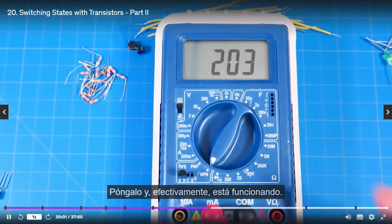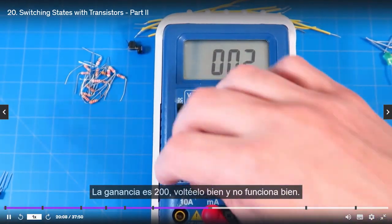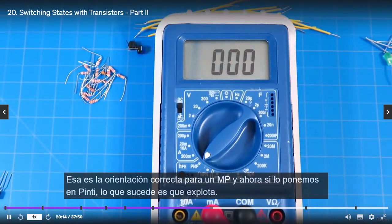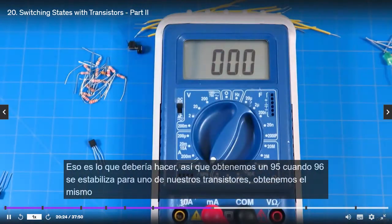Pop it in, and sure enough, it's working. The gain is 200. Let's flip it around, and it doesn't work. So that's the correct orientation for an NPN. Now, if we put it in PNP, what happens? Does it explode? No, it just doesn't work, and that's what it should do. So we get 195, 196 as it stabilizes for one of our transistors.